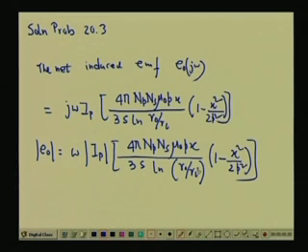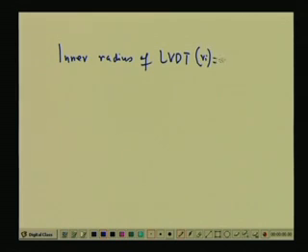We know from the text that the ratio r I by L A typically is 0.05, both in meters or in centimeter. Therefore, the inner radius of the LVDT assembly, that means Ri, will be equal to 0.05 into 20, because 20 is the length already given, the length of the primary is 20 centimeter. So, it is coming as 1 centimeter.